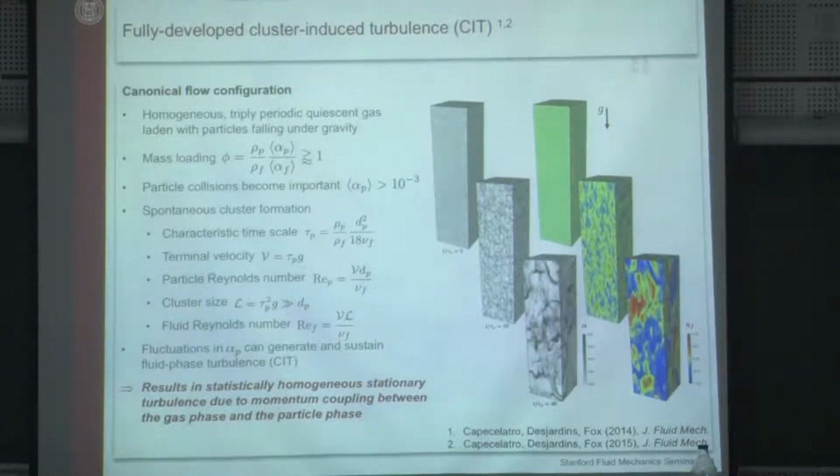Now we have a surrounding fluid that, of course, is going to start getting entrained downwards because of the downward motion of the particles. So this system, if we don't do anything to it, will blow up, right? The particles will fall faster, the fluid will keep getting entrained and fall faster, and this thing will never stop. So what we're going to do is constrain the flow rate of the fluid to be on average 0.